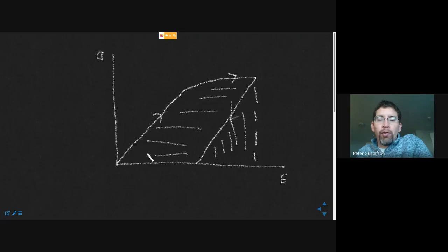So what's going on over in this region with the horizontal lines is actually at the atomistic or more at the grain boundary level, what we're getting is dissipation of energy as you're doing maybe phase transformations or slip planes are occurring. You're moving atoms past each other in a way that's not recoverable.